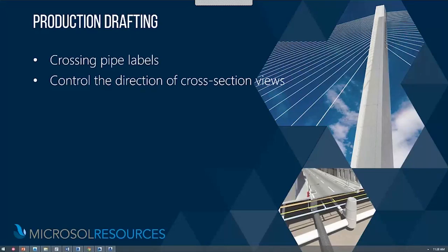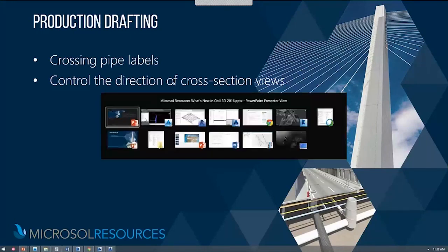So this is particularly useful if you've ever been doing any amount of flood analysis inside of Civil 3D, either using the Army Corps of Engineers tools or using the river and flood analysis tools that come as part of your subscription advantage packs inside of Civil 3D. So essentially, when you're plotting sections of river, sometimes the left bank needs to appear on the left side rather than just the way the alignment is oriented. So the ability to flip those is brand new in Civil 3D. So to give you an example of those two, let's go ahead and go back into Civil 3D.